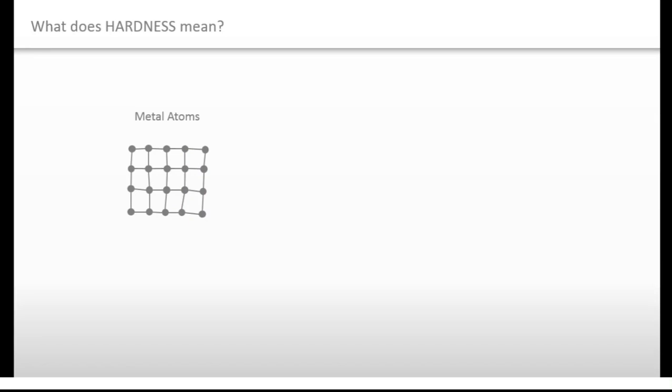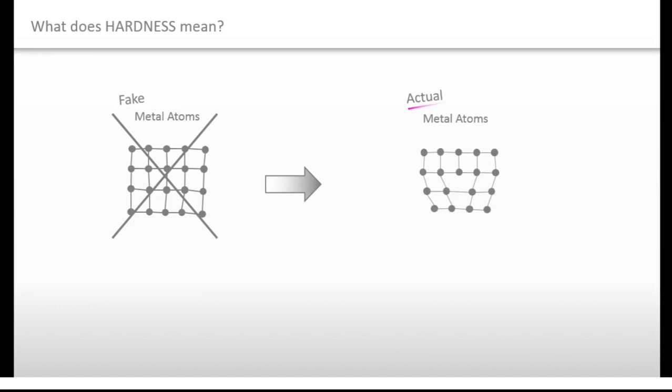Okay, in the first place, this structure does not exist. Actual metal has a defect like this. This defect is called a dislocation, and it is usually expressed by this symbol. If you apply force on this metal, the dislocation will move, as you can see. So, if a piece of metal has plastic deformation, it will be the same as dislocations